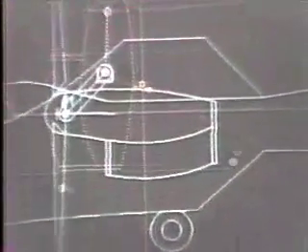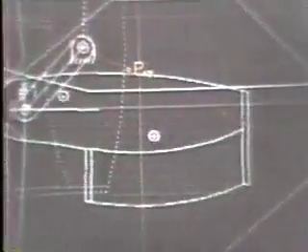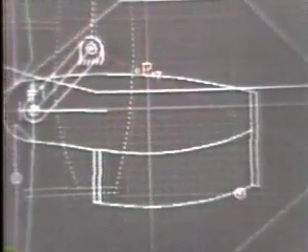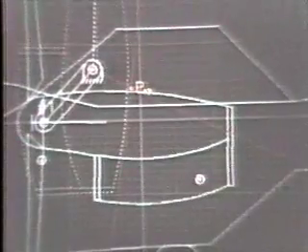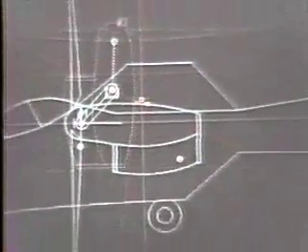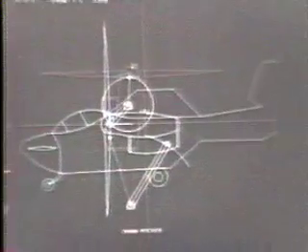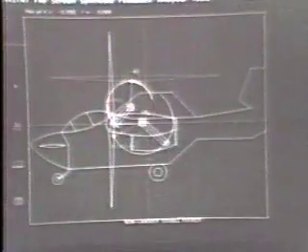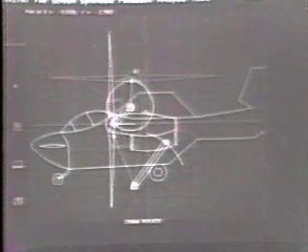The designer is now positioning a second moving pivot. As he moves the moving pivot around at various points on the rotor body, the locus of possible fixed pivots is shown in this case as well. As the designer goes to choose the fixed pivot corresponding to the second moving pivot, the complete 4-bar linkage is shown.